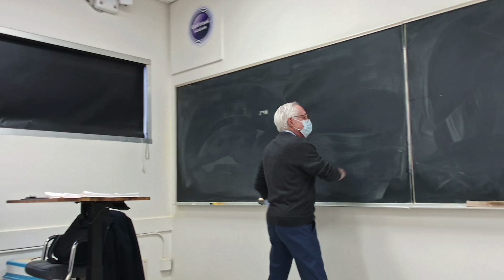From this I see that h_in + V_in²/2 equals h_exit + V_exit²/2, right? Just by dropping those. In many, many cases, kinetic energy is negligible compared to the amount of enthalpy that the gas or fluid is carrying. Therefore, generally,